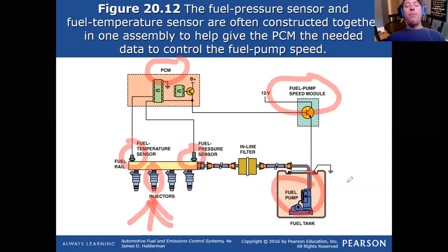Now, of course, you should be wise enough to also note the other drivability issues in all of these situations. So those drivability issues are going to vary drastically as well, because obviously if we have an injector that's stuck wide open, imagine the black smoke, the misfire, hopefully customer drivability concerns. There's going to be a lot of other things that play into this. So sometimes just the effect, like the actual customer complaint, is what we're using as our most valuable insight to this. But these are topics for other days with advanced diagnostics. We're definitely going to be talking about this type of stuff more, how to diagnose these systems. But this is just the overview, and hopefully that's a decent explanation there.